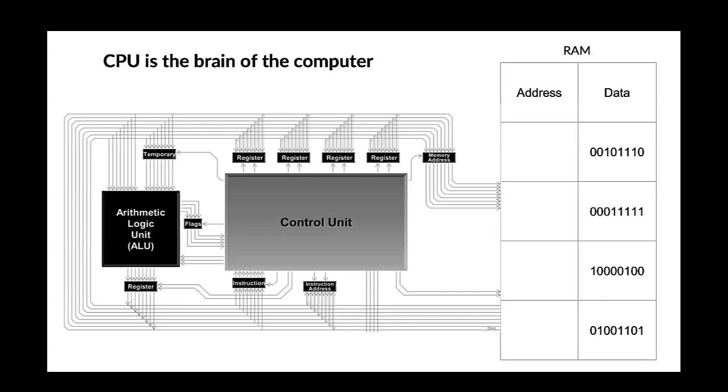As you can see on the screen, CPU has wires, registers, and some other components like ALU, Arithmetic Logic Unit, Control Unit, and Cache. The Control Unit fetches internal program instructions from the main memory to the processor instruction register, and it generates a control signal based on the contents of this register to supervise the execution of these instructions. It's the center of operations. It receives and decodes instructions and then sends out commands to the other components. Registers are very tiny memories that are very fast.